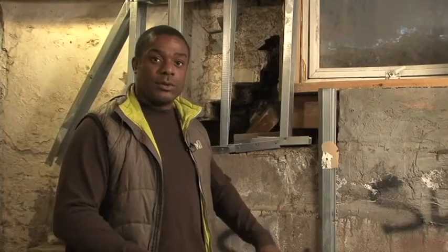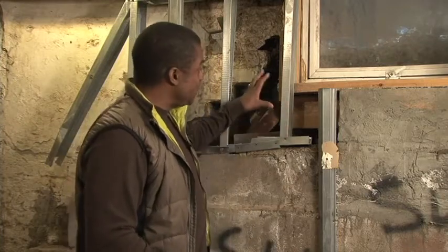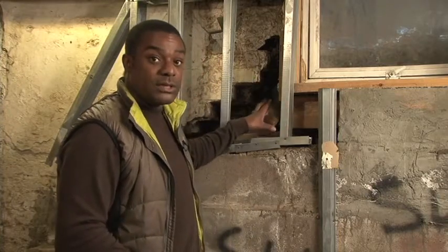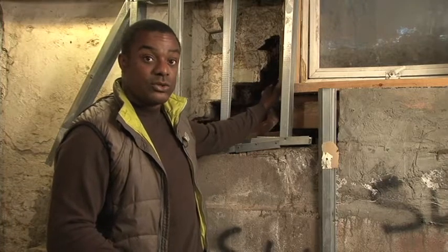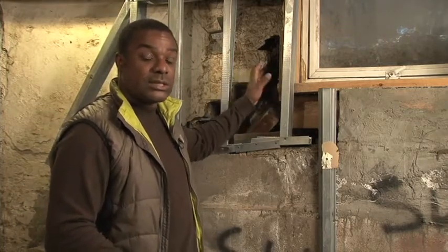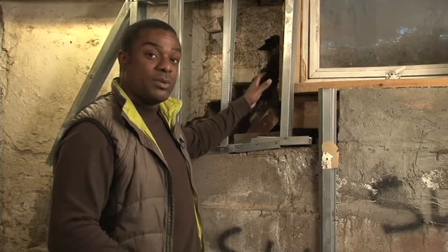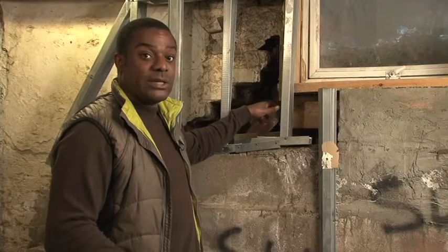When we look at our basement walls, we're noticing quite a few problems. First, we're not seeing any insulation on the foundation walls. In addition, where pieces of our foundation wall are missing, we can see exposed dirt on the other side. And in that exposed dirt, we're seeing discoloration where water has come in and is probably building up behind the foundation, maybe even displacing the foundation.